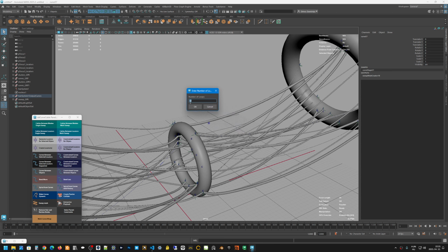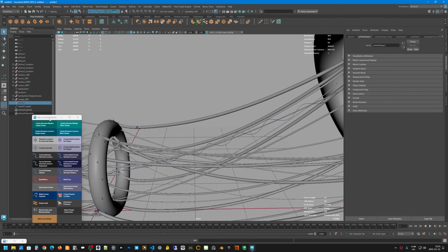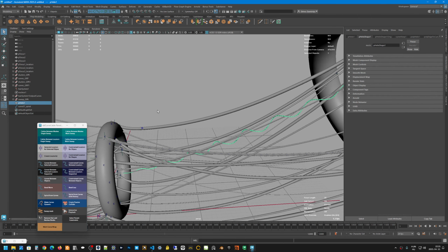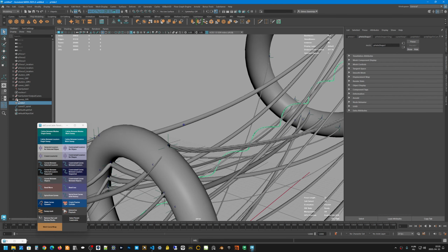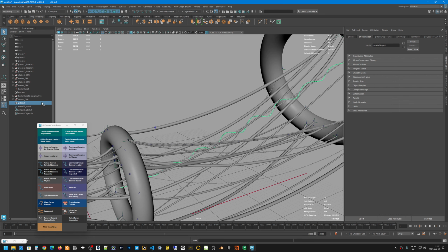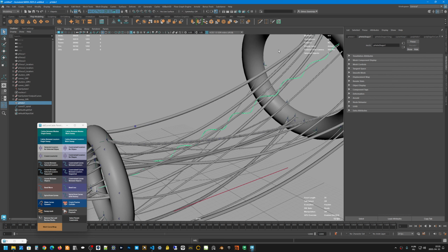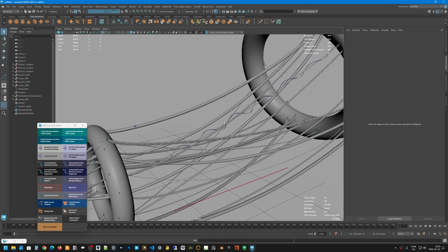You can actually use 10 here, and then you can go up to 30 if you want. Radius 20. Okay, so this is the spiral. I'm using this trick to create a helix and then wrap that helix with the curve wrap node around the curve, and then I convert one loop to a curve. So that's what you see here.